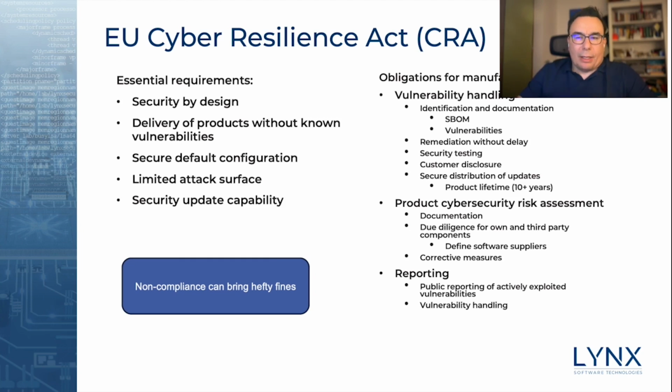in some way. You have to provide a secure default configuration. You need to implement security features to limit attack surface. If you have different open ports, you have to implement an approach to limit what can be connected to it. And then the device needs to have a capability to update software in place. So if any vulnerabilities are discovered for the software used in the product in the future, the device needs to have a way to accept an updated firmware, whatever that is, Linux kernel or file system applications, and then flash it, right, to close off the security loopholes.